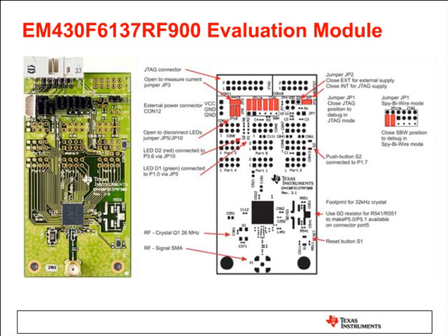You've got these headers, which we provide. We provide the little pins that you can solder onto there. And we bring out every pin on the device, of course, except for the RF side. But it's cool because you can use this as a reference design for a whip antenna. And so we have code examples for this, RF code examples that show how to communicate with the radio.